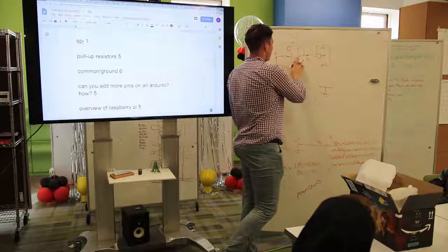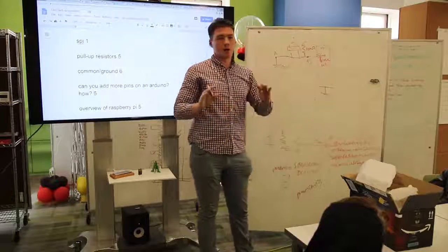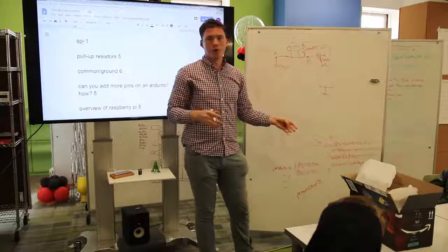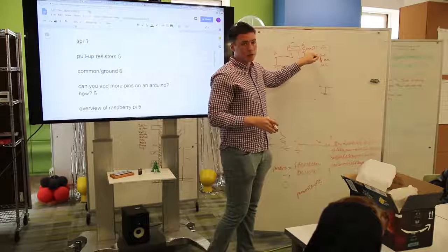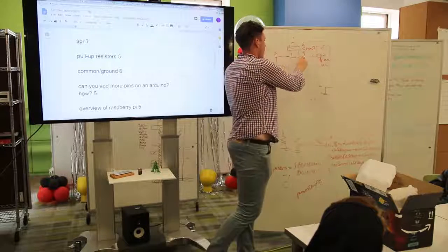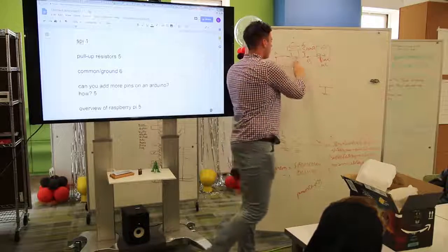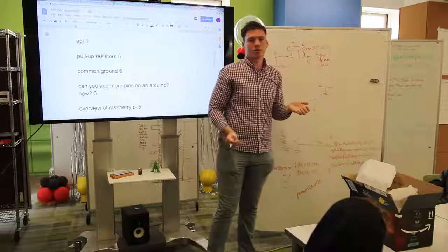So instead what we do is something slightly different. Let's say this is the unpressed state. We have a resistor and ground, which means we're not going to have that massive current. We're not going to have a short anymore. So basically, the 5 volts will all drop across the 10 kilo ohm resistor now because it has a direct path to ground, and the input will see that direct path to ground. When it's unpressed, weak connection to 5 volts, no connection to ground, so it sees 5 volts. Does that make sense?